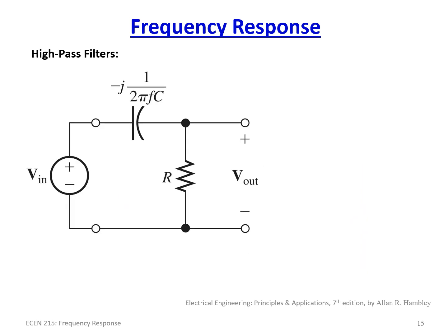So for high-pass filters, I won't go through this in as much detail. You can run through the math as well. It's basically the same process. And of course, you can do these with inductors as well, and just change the position of where the inductor or the capacitor is. In the case of a high-pass filter, you put the capacitor in place where the resistor was, and the resistor is now where the capacitor was. And of course, it's completely inverse if you want to use an inductor.